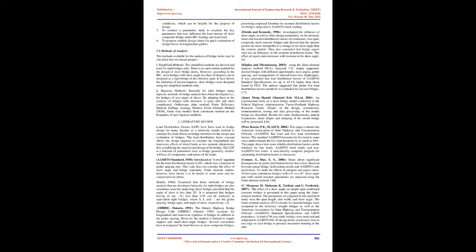1.3 Methods of analysis. The methods available for the analysis of bridge decks may be classified into two broad groups. 1. Simplified methods. The simplified methods are derived and used for right bridges only. There is no such similar method for the design of skew bridge decks. However, according to the IRC, skew bridges with skew angle less than 20 degrees can be designed as a right bridge of the effective span.